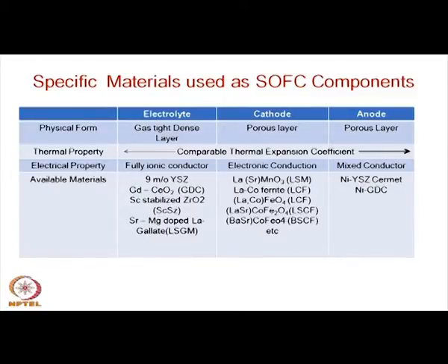Now, one thing also is important here, what will be the thickness of the layer? Thickness has a very important bearing on the overall performance of the cell, because the higher the thickness, the higher the resistance, which gives rise to higher internal impedance of the cell. So, one cannot draw a large current if one wants to.